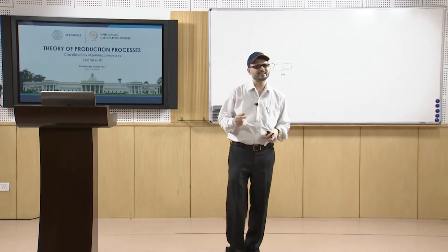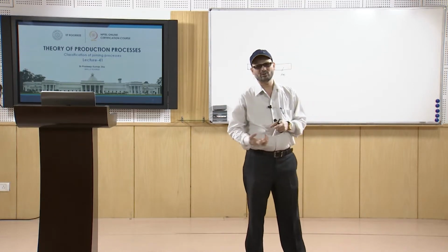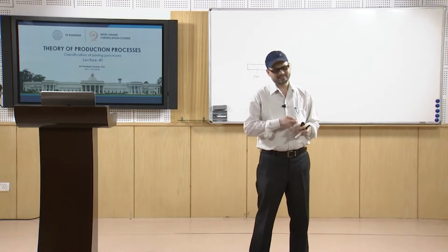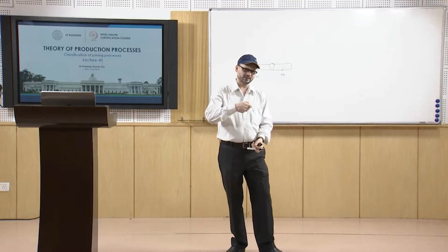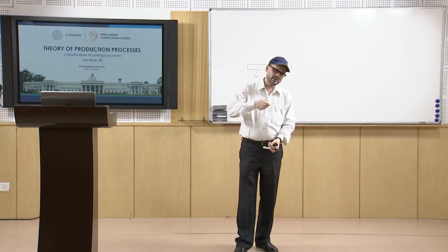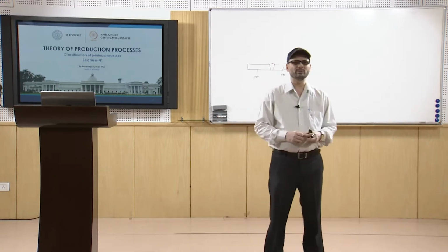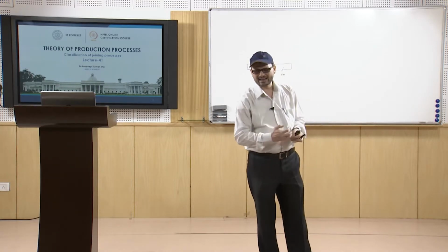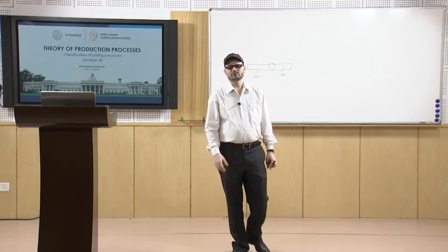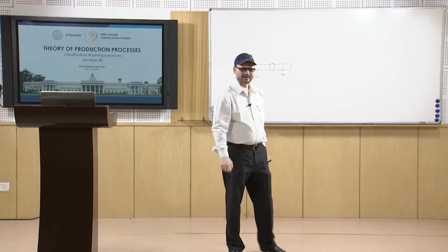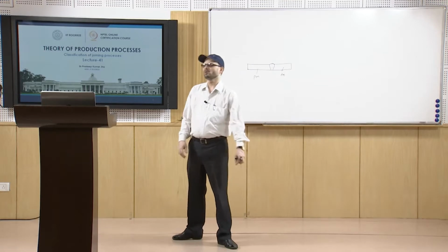In these cases, one electrode is used and the workpiece works as the other electrode, and you go on producing the arc between the electrode and the workpiece, and this electrode goes on getting consumed as the welding process is carried forward. That is why after some time you have to change the electrode. So that is consumable electrode.